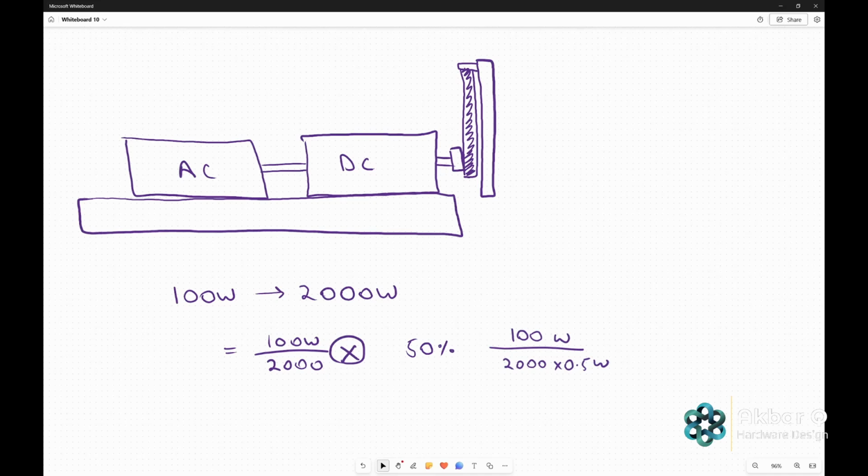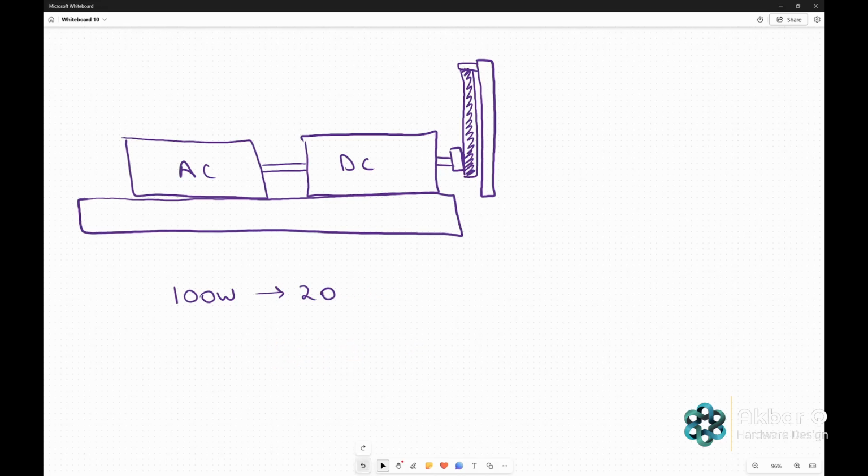So in short, we have to isolate the AC machine from the DC machine when we characterize it. So the first thing we have to do is to characterize the DC machine. To characterize the DC machine, we have to get, first of all, a few baselines. The first baseline is the dead weight of the motor: how much power is wasted by the motor simply spinning.